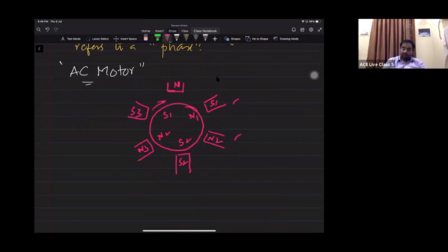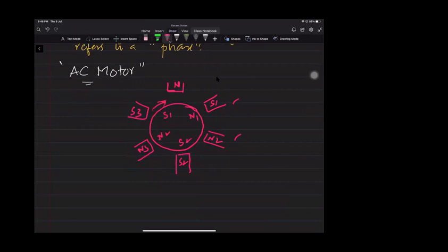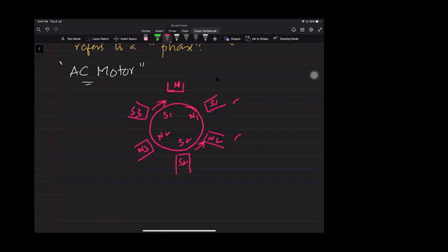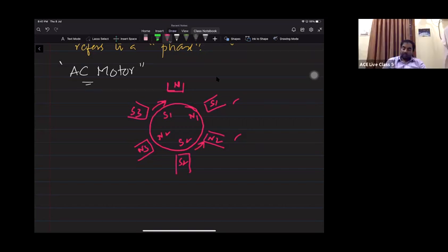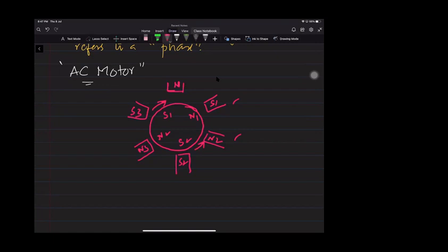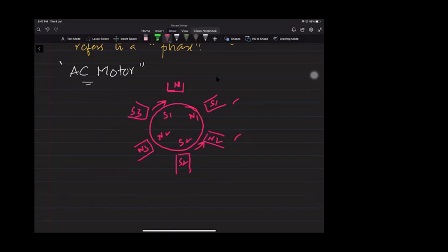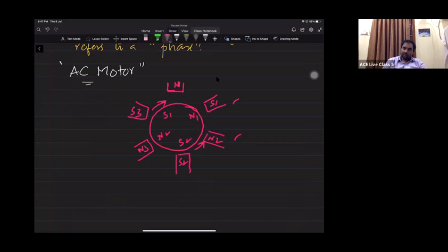See, what is existing between these two? Just taking one: repulsion between S and S. At the same time, what is existing between these two, S2 and N2? Attraction, sir. Then in which direction are both acting? Opposite directions. Then what happened to the rotating part? Zero. It does not rotate. Right? You can try for any number now.